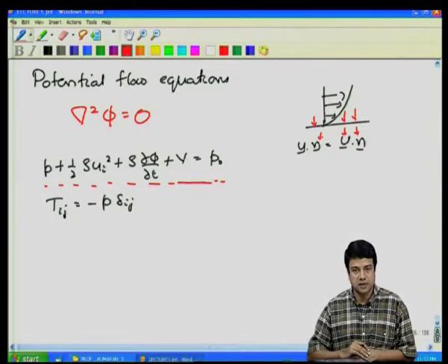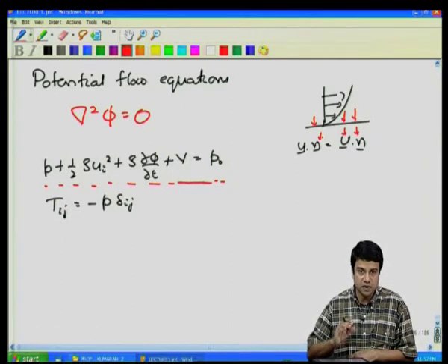So, this is the way that you would solve in case there were velocity conditions specified at the bounding surfaces. In case pressure boundary conditions are specified, it gets a little more complicated. You have to solve both of the equations, the Laplacian of the potential equal to 0 and the pressure boundary condition, with some initial velocity, and then correct that until you get the pressure correct.